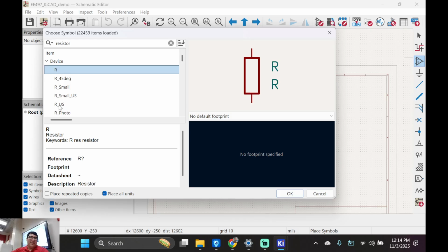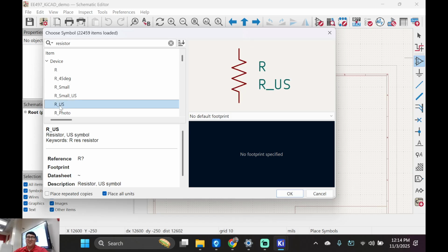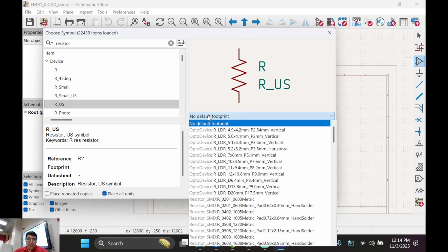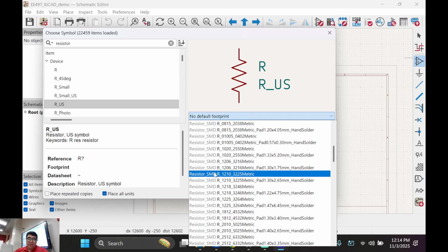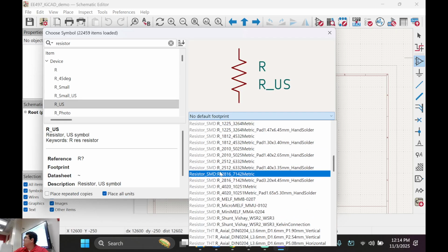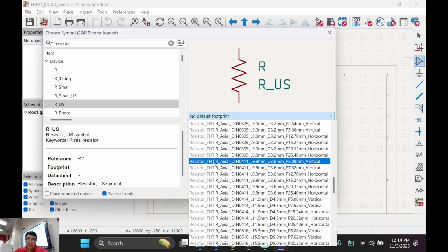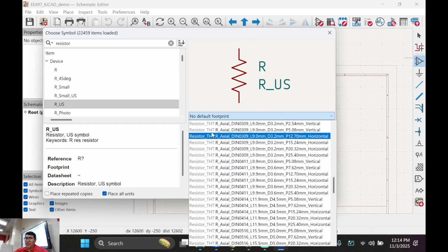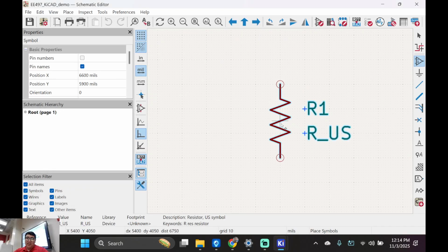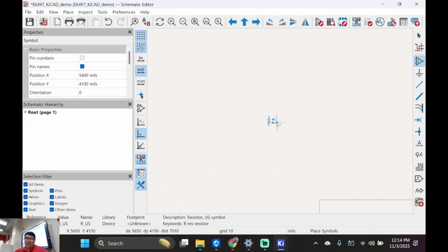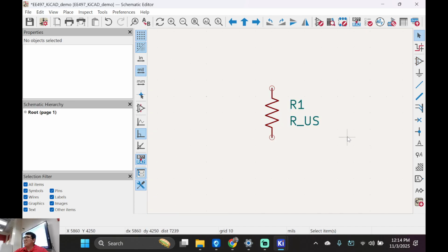For me, I like going with what I know. It looks cool. Double click. There's a footprint right here, and some of them have a footprint. You can assign a footprint. There's SMDs right here. You know what SMD stands for? Surface mounted device. And then there's THT, through hole. But right now I'm just going to click a resistor. I just need a simple resistor. Scroll wheel to zoom in, boom, you've already done it, congratulations.